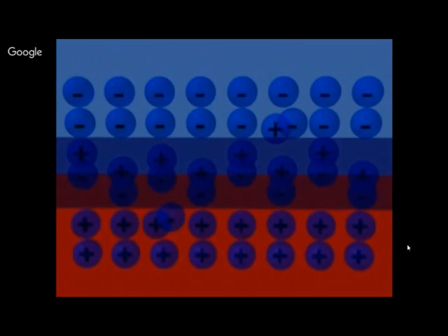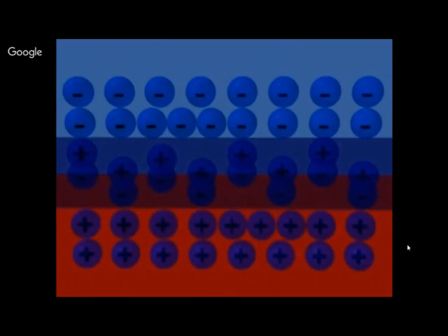If this happens in the electrical field, electrons are moved to the N-doped layer and holes are moved to the P-doped layer. The system will fall into a state of imbalance because of an excess of electrons in the N-doped layer. The corresponding holes can be found in the P-doped layer. It goes without saying that these free electrons and free holes try to combine. However, the electrical field does not allow such a condition.